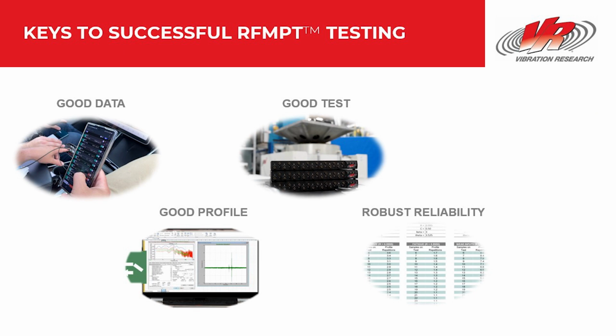So the keys to a successful rapid failure mode precipitation test are, first of all, good data. We can get good measured data using Observer 1000 or another data acquisition system to measure data on our product. And that's for vibration data, but we also need thermal data, ideally corrosion data, humidity data, electric load data, number of mechanical cycles, etc. So we need good data, or the best data that we can have available to us to correlate to that end-use environment.